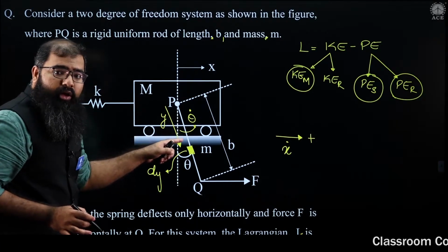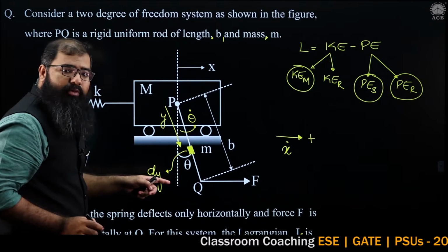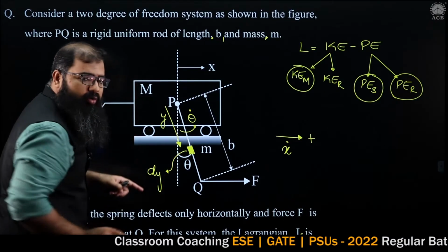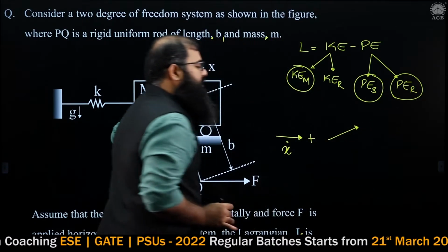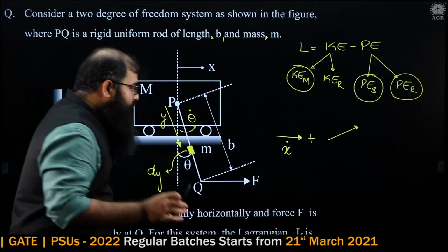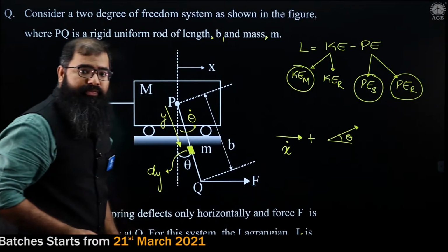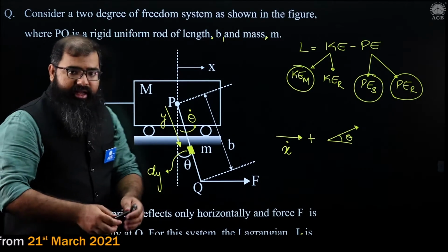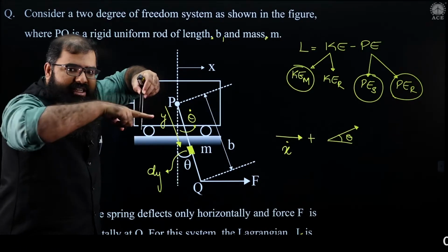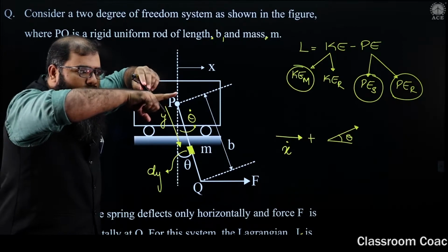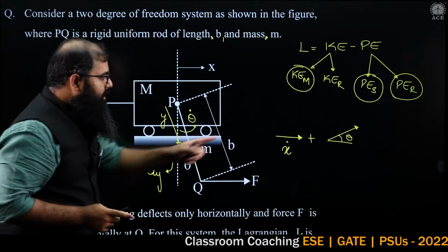Now, this angular velocity is going to give it a tangential velocity. The tangential velocity is supposed to be equal to how much? Radius multiplied by theta dot. So, let us say it has a tangential velocity vector in this direction, which is inclined at an angle theta with respect to horizontal. Why theta with respect to horizontal? Imagine if the rod was vertical. Then the tangential velocity is exactly horizontal. If I incline the rod by an angle theta, even the velocity has to get inclined by angle theta with respect to horizontal. Therefore, angle theta.